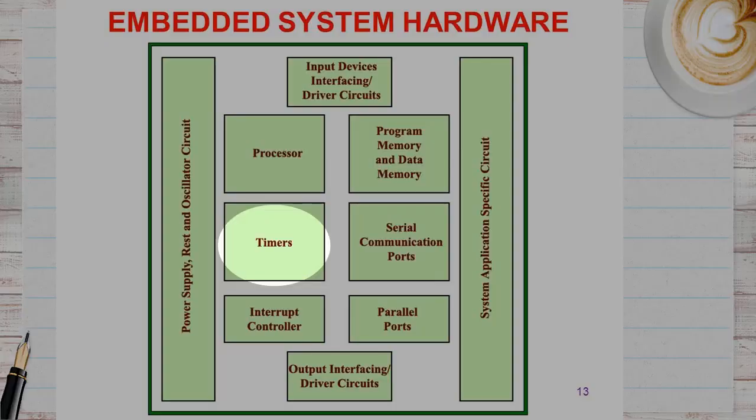A timer circuit is suitably configured as the system clock, which ticks and generates system interrupts periodically. A timer is suitably configured as the real-time clock that generates system interrupts periodically for the schedulers, real-time programs and for periodic saving of time and date in the system. To schedule the various tasks, and for real-time programming, a system clock is needed. The clock also drives the timers for various timing and counting needs in a system.